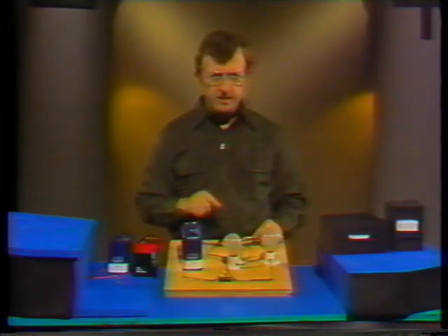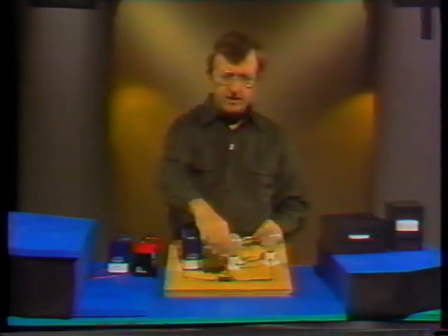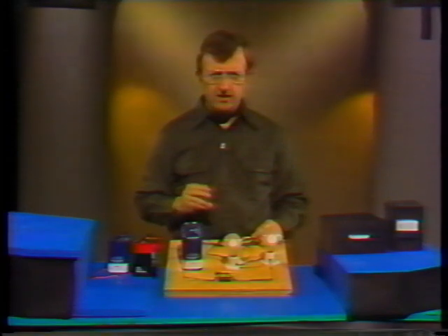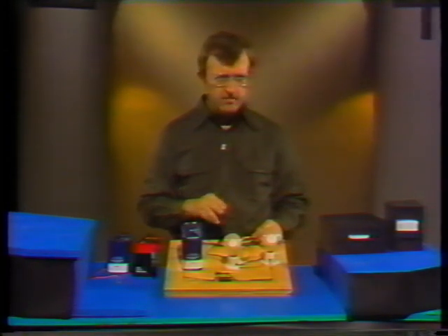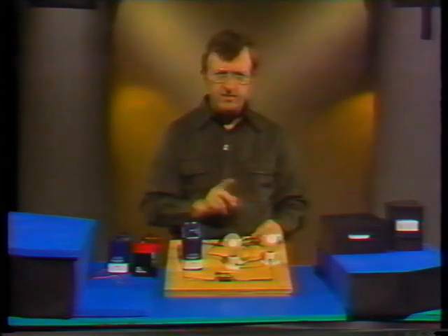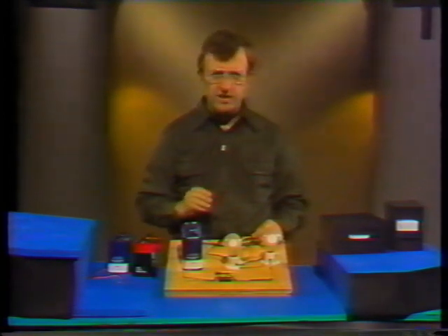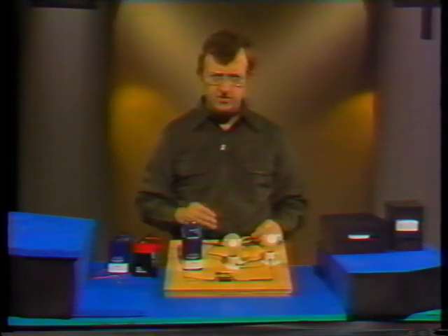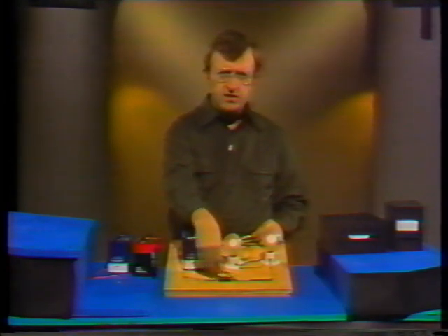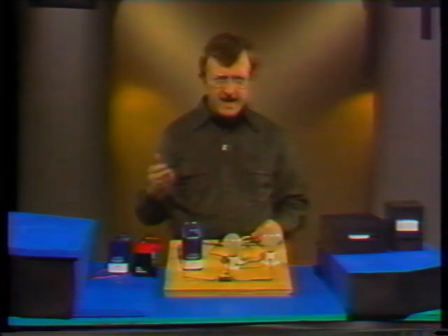Switch is open and the light bulb is in. Now when we close the switch, the reading is 1 amp. It worked out. Not only is there less current going through the meter, but the light from the 2 bulbs is dimmer than the light from the single bulb. And that's another indication that the current has been reduced. So we can figure that resistances hooked up in series add up.